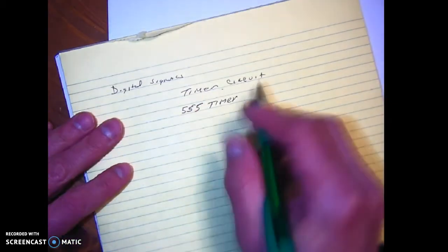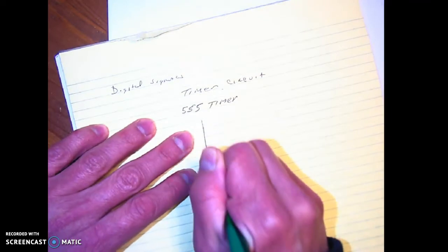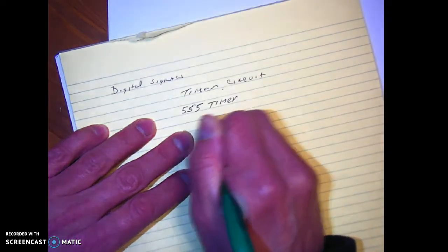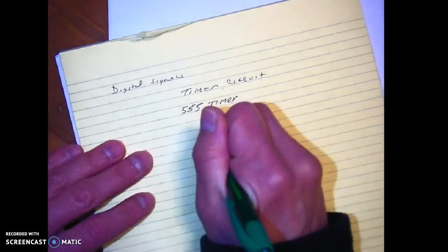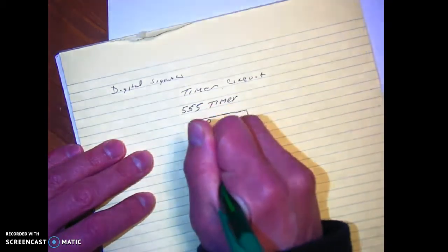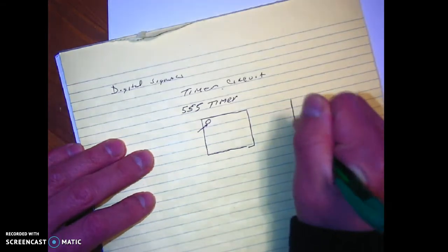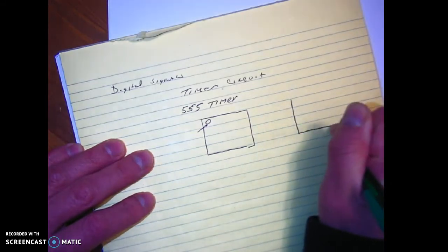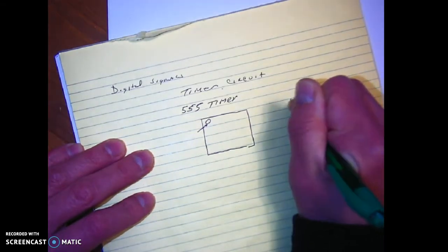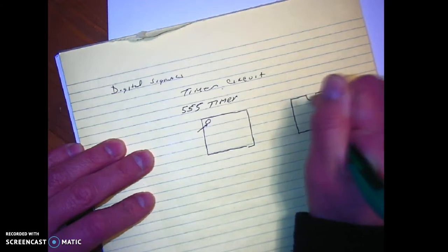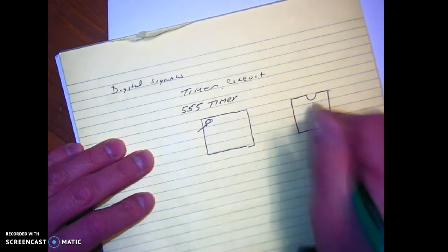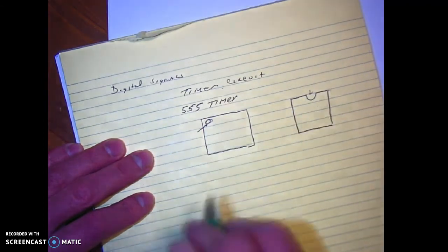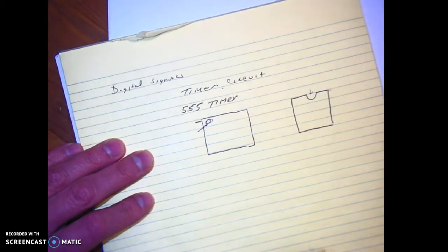But basically what it is is a chip, an integrated circuit, and that's what IC stands for, integrated circuits. And on integrated circuits, you'll either have something with a little indentation right there, or you may have something that looks like this with a little dot. Well, when you have either a little dot here that's indented or this little hub right here, pin 1 is always to the left side of it.